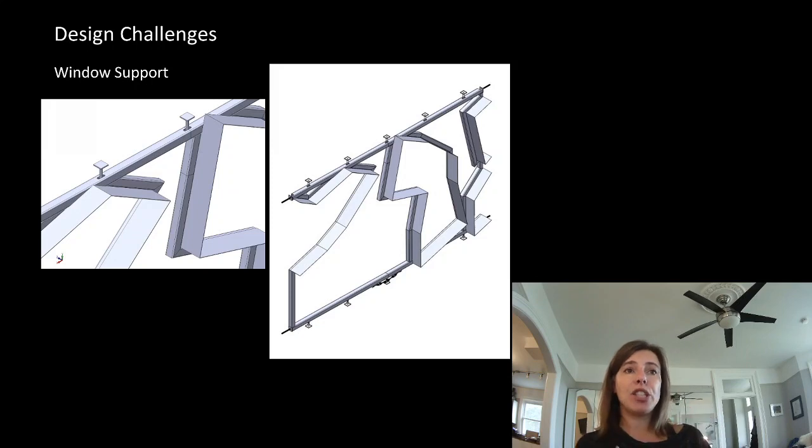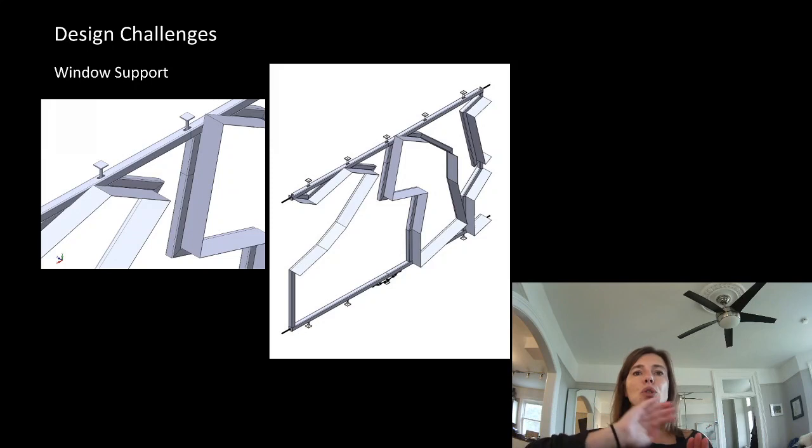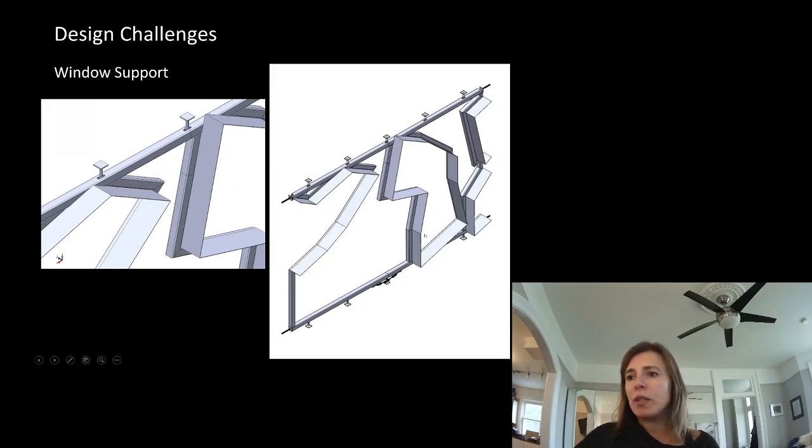We had another added challenge, and I kind of alluded to this, where we said that the windows are actually, the whole facade was 450 millimeters outside, plus minus, from the edge of the concrete. The facade is pretty light, and we ended up having them do like our single stud, and then they built it up with 2 layers of light gauge kind of steel grid to pick up the main facade. Our problem is the windows, where we had nothing that could stack out in these open zones. We needed something that could frame the windows and be absolutely perfect.